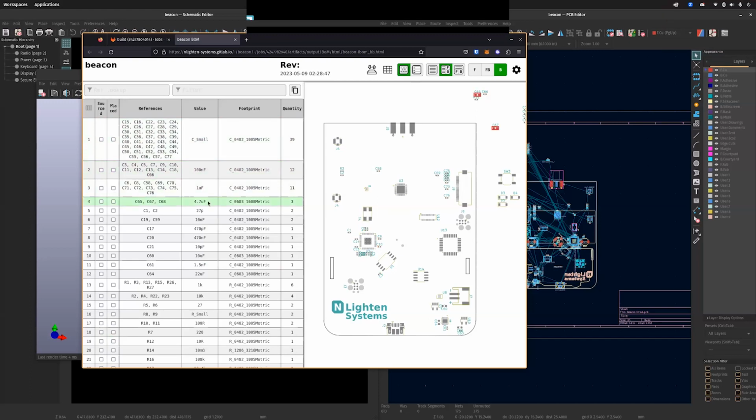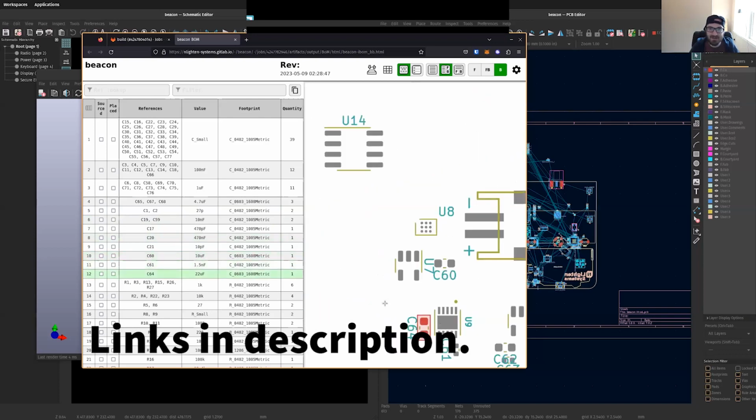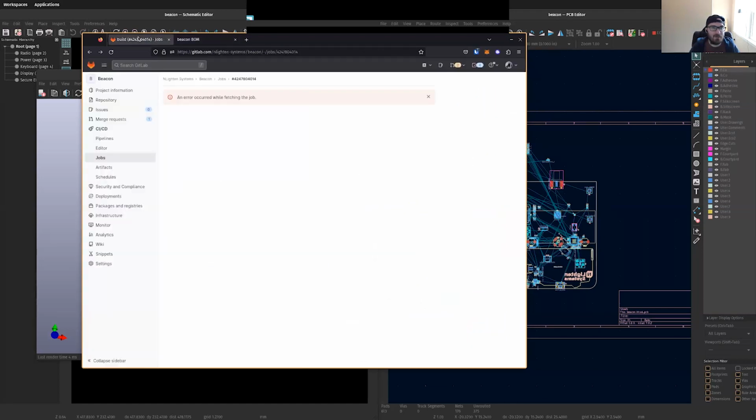If you put the XY positions in CAD, the vectors, you've got a pick and place machine ready to run. Yep, 100%. And that's another one of the outputs we can enable here. Like Travis was saying, you can go through the components one by one and see how it's highlighting, and it can tell you where to place it. It's great. So that's kind of just one of the outputs.